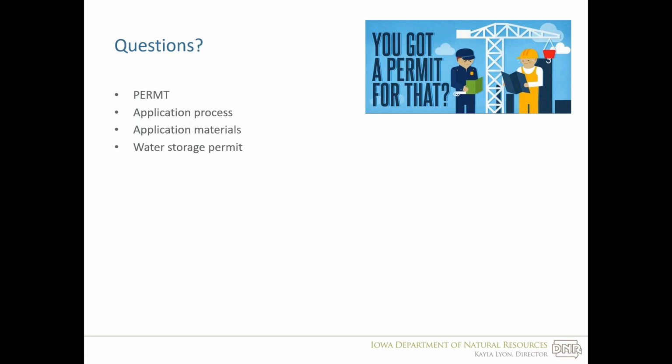Okay. There was a question about the regulatory thresholds and if it has to meet all of the requirements or any of the requirements. For the three? Yeah. It's an or. So if it's 25 foot tall, it is a regulated dam, unless it has less than 15 acre feet. It doesn't have to be 25 foot tall and 50 acre feet. Okay. I think that's what they're asking.